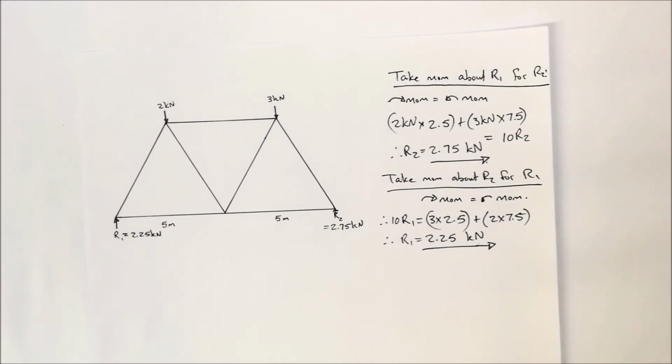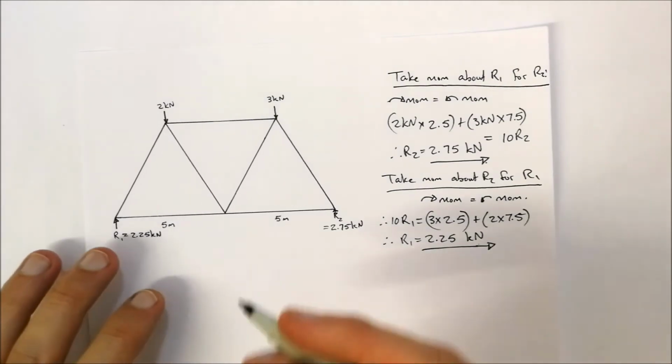One of the things I'm going to do now is make all the beams to be considered as struts. I know that there are some that are considered as ties, and you'll see we are able to identify whether, if we made a mistake in terms of struts, they should be ties. So I'm going to make everything struts.